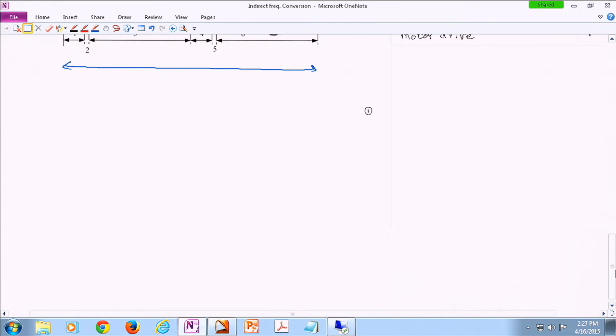Probably. Go ahead. So if we are continuously switching on and off this AC circuit, will there not be surges or something like that? There will be, yes. So that would be another problem to solve, for instance, adding low-pass filters to the input side.